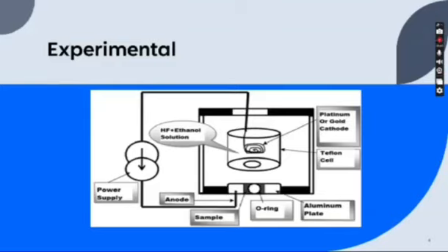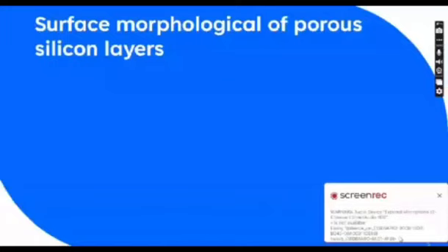It is evident that the diameter of the O-ring controls the diameter of the resulting porous silicon patch. This remains valid when edge effects are not taken into account. To ensure the reproducibility of the morphology of the layers and to be able to control the porosity and thickness, the dissolution was carried out with a constant current flow between the two electrodes.